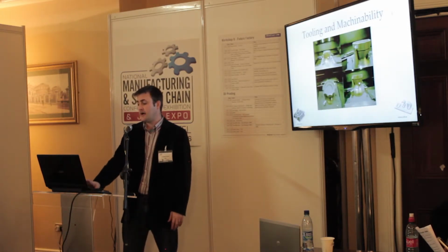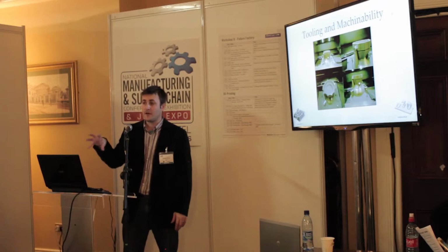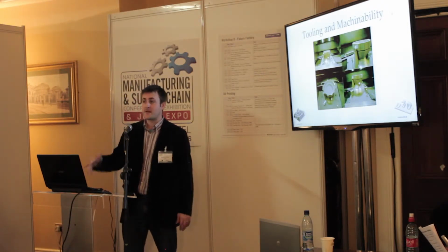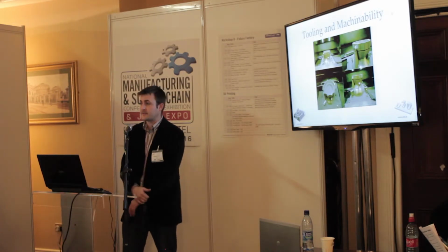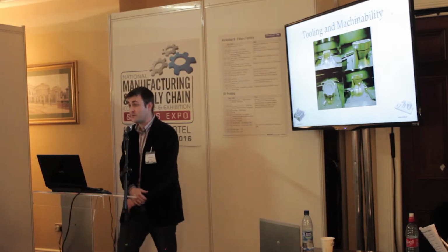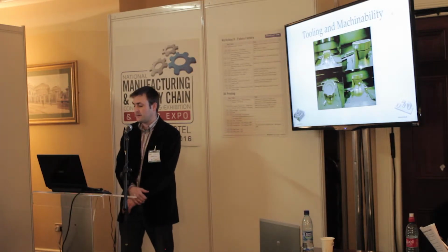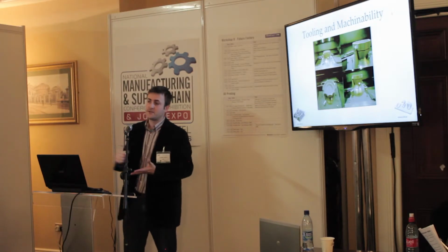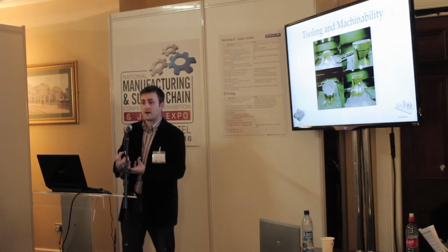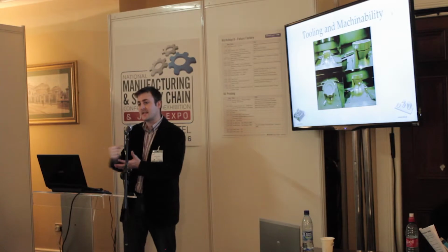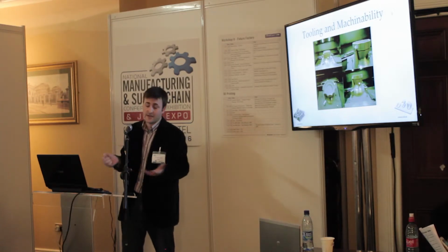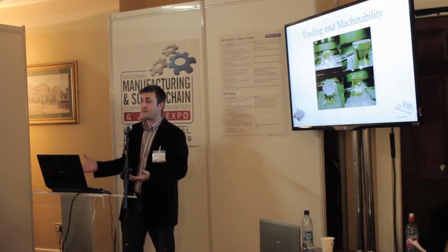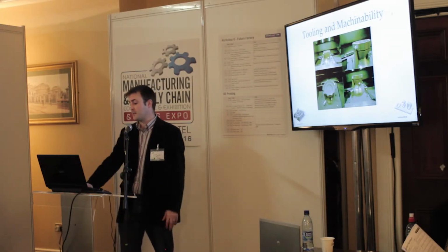This is an example of how well the machinability works in 3D printing. This is a rocket engine by SpaceX. It's printed in Inconel. It's a nickel chromium superalloy, and it is very difficult to machine. Traditional tooling, once it works the part once, it starts hardening, and it means that it can't be successively manipulated and machined using traditional CNC approaches. With 3D printing, because you're just melting the powder, building it up layer by layer, you get improved designs.